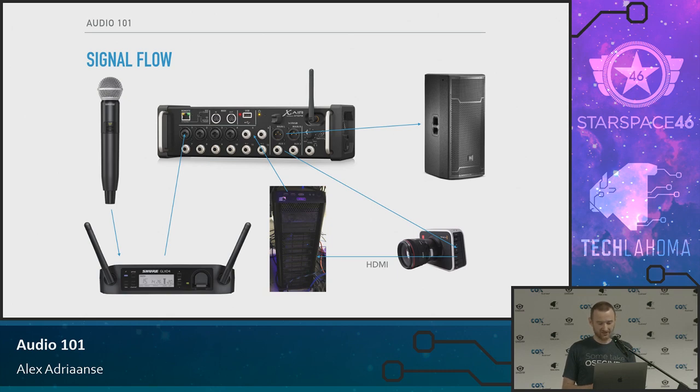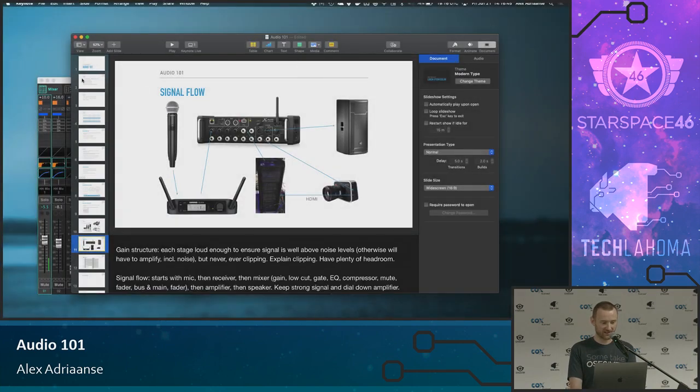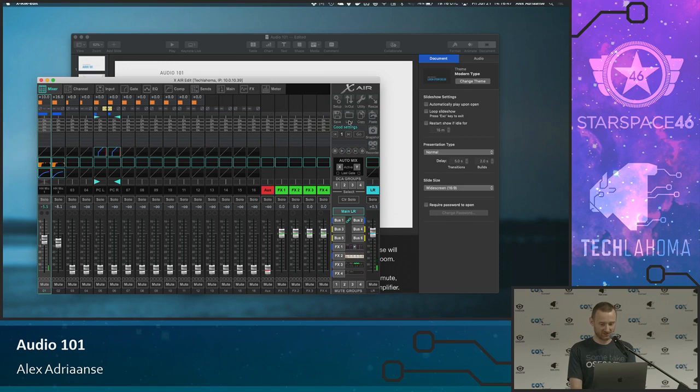Oh, and then the other thing that I keep in mind when setting signals is that I want to make sure I have plenty of headroom. And what that means is the amount that the signal can increase before it starts clipping. So clipping sounds bad, or is bad. It's when you're basically overloading the circuitry or digital signal processing, and it cuts off the waves and it sounds distorted. So if you're wondering what it sounds like, I might be able to demonstrate.